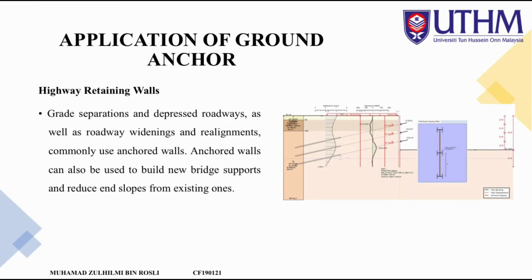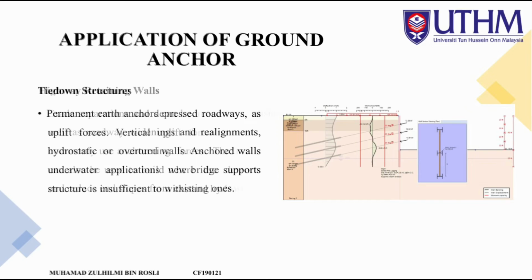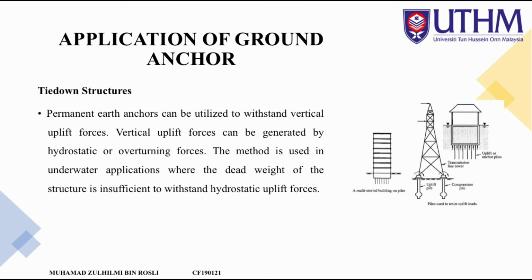Secondly, highway retaining walls. Grade separations and depressed roadways, as well as roadway widenings and realignments, commonly use anchored walls. Anchored walls can also be used to build new bridge supports and reduce slopes from existing ones. And lastly, tie-down structures. Permanent earth anchors can be utilized to withstand vertical uplift forces. Vertical uplift forces can be generated by hydrostatic or overturning forces. This method is used in underwater applications where the dead weight of the structure is insufficient to withstand hydrostatic uplift